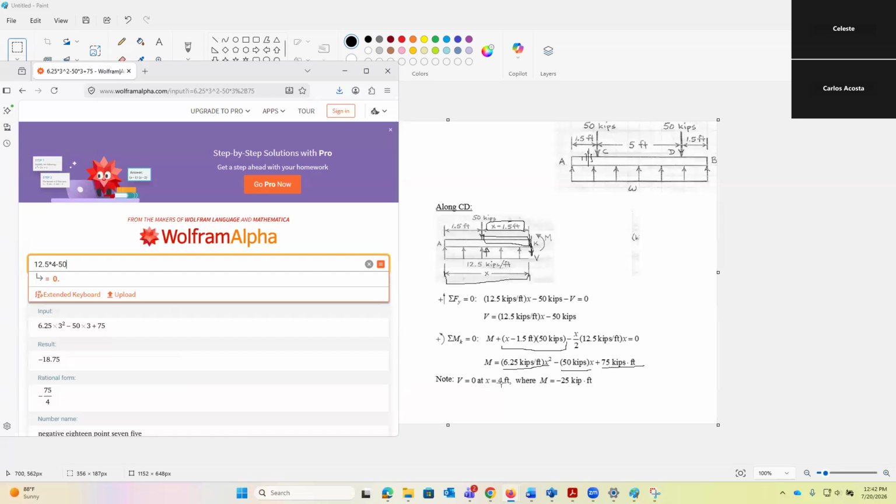The reason why this is a good point to choose is that with v, the shear is 0, because we can use that as a crossing point on the plot. You'll see in a minute. If you also use 3, then you write that number down. So it's negative 12.5. At 3, v is negative 12.5 kilo psi.